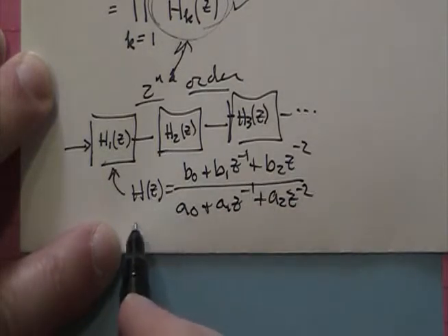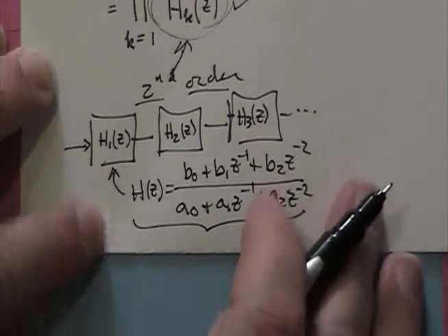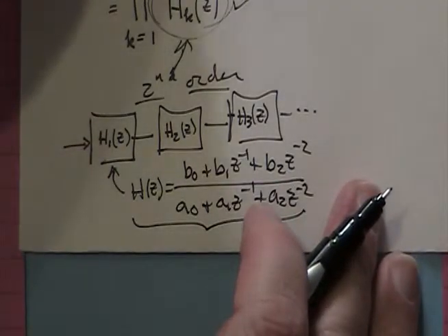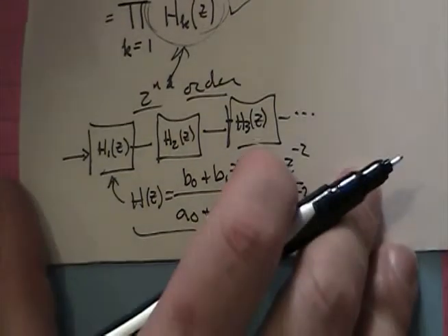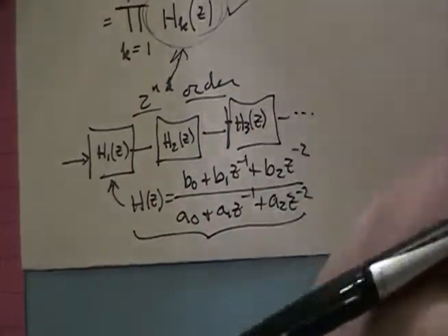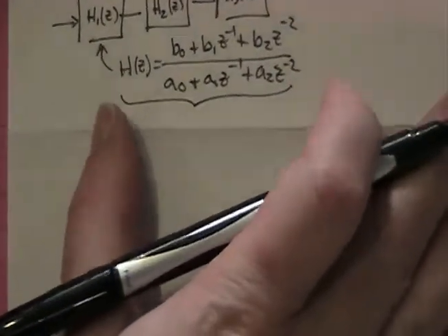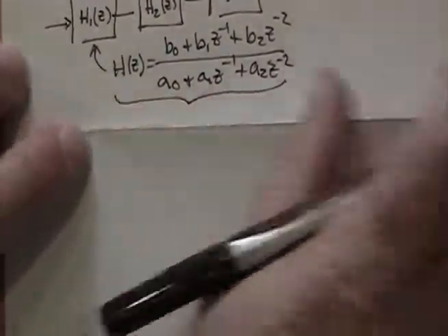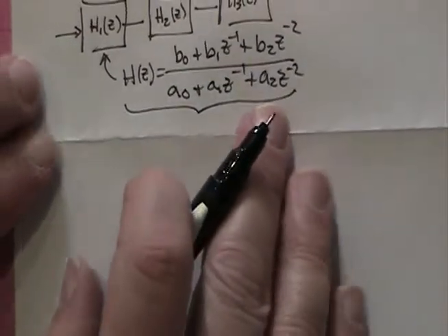Okay, so there's my generic second order transfer function. Usually when I'm dealing with rounding errors, our starting assumption is that we've already taken that step, and 9 times out of 10, that's enough to get around many of the rounding errors that you can have, at least for a floating point processor, not necessarily for an integer processor.